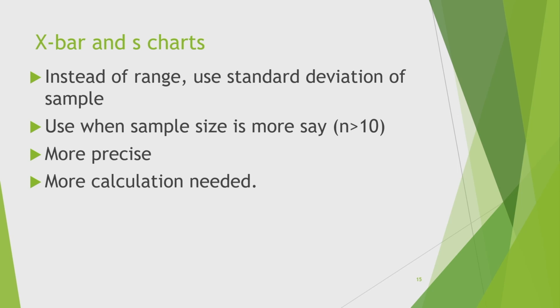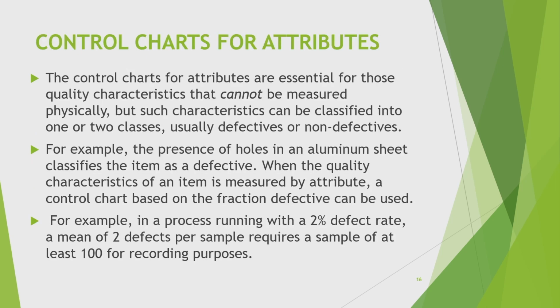Instead of range, you can use standard deviation, but generally it is preferred when the sample size is larger, say n should be greater than 10. It is more precise, but more calculation is needed. Then this is the control chart for variables.